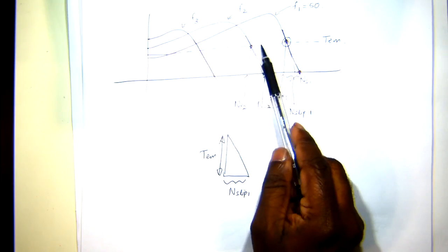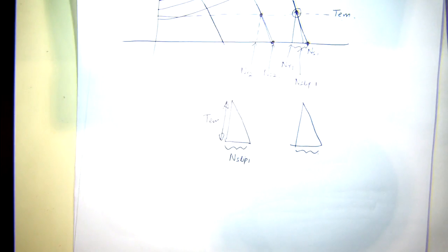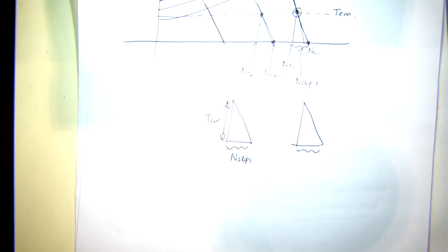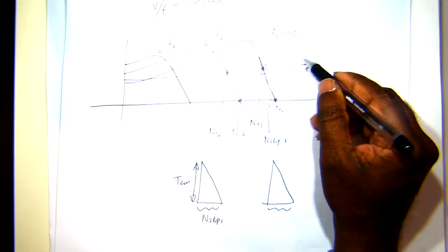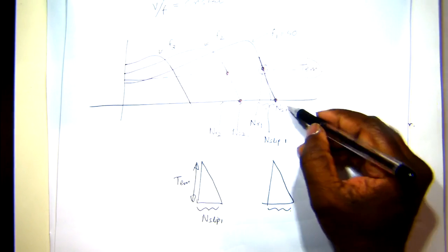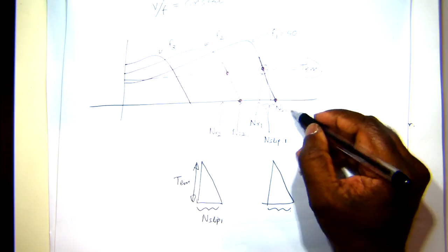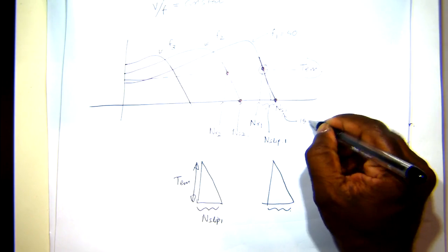So if you are changing frequency with voltage, if you want to achieve the same torque, the slip has to be the same as well. That concept is used if you want to operate the machine at a certain load condition. Let's say, for example, at 50 hertz, the induction machine produces this amount of torque, excited at 50 hertz. If it's a 4-pole machine, this will be 1500.